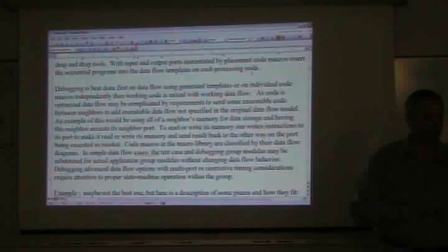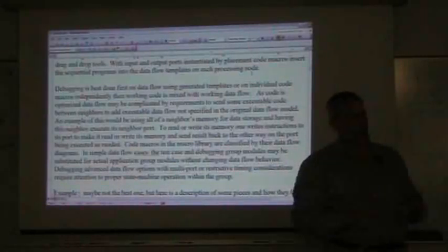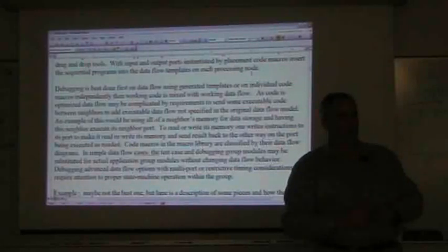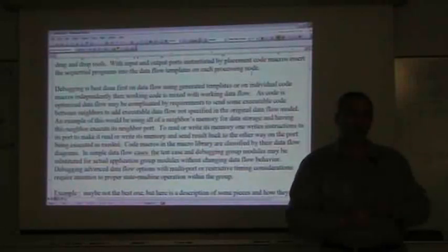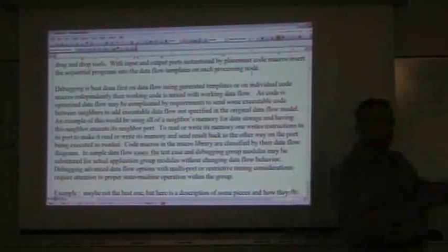Very simple thing. Now, I put a couple of nodes upstream. And these things are just doing trivial things. One of them takes the number sent to it, now that's been linearized from the A to D, and it breaks it down into 6 decimal digits. Then it sends those 6 decimal digits to the next node.